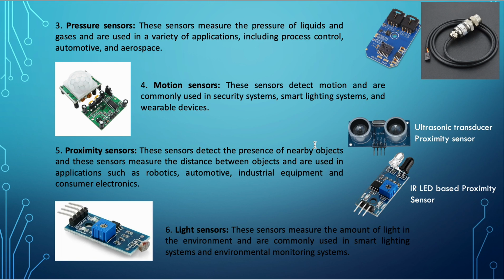And depending on the situation, if it is a dusty situation, if there's a lot of dust, or if there are too many bright IR lights available or something like that, we can't use the IR LED. But if it is more to do with sound, when it is an industrial level application, and in a steel manufacturing factory, ultrasonic will not perform very well because the sound will be disrupted big time. So for those, IR sensors are much better.